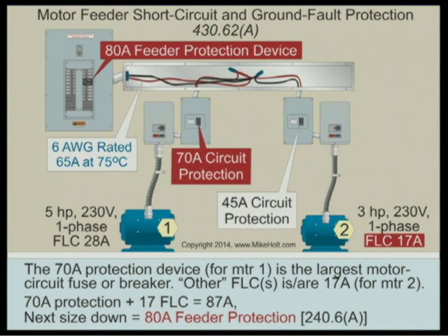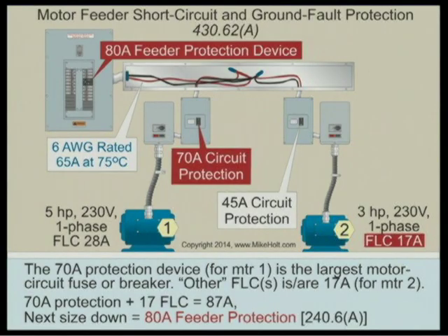Hey, Mike. Yes. I know you said this, but I really want to point out that when you do size the feeder protection, you're sizing it on the actual device, the largest actual device. So that's a 70 amp circuit protection on the largest device. Yes, you saw that. I understand what you're leading up to.